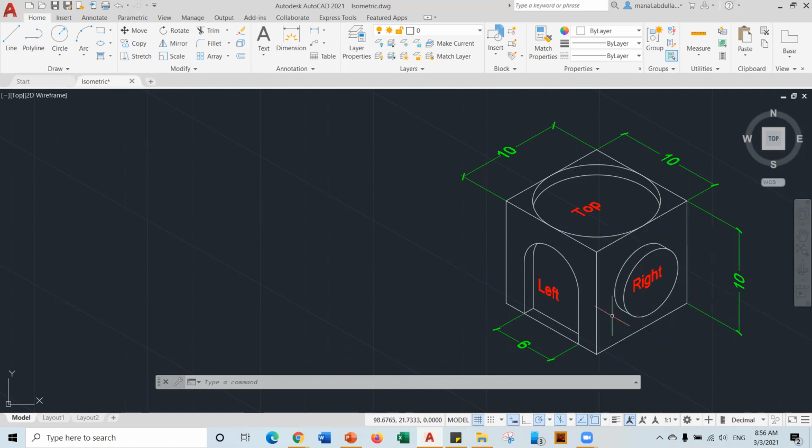So if you are drawing on the right side, make sure you put it on the right, so the isoplane should be on the right. Let's start with the right. And as I mentioned before, you can press Control E, F5, or right. If it's not working, you might need to press the Fn button on your keyboard as well, along with the F5. Now, let's make it isoplane right and see here, watch the grids aligning.